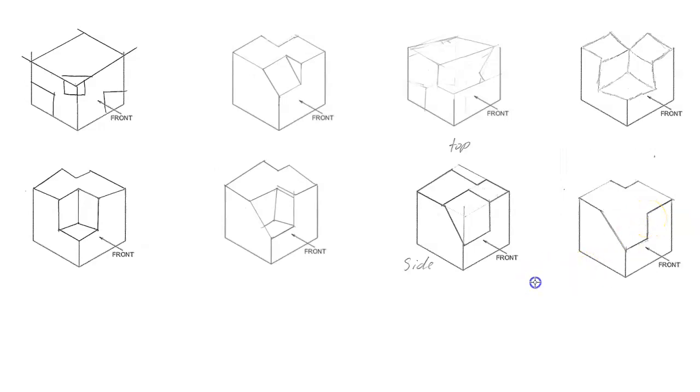So I think that's a pretty good range of what to expect, and hopefully you've learnt some of the things about how we approach where the marking scale is. And if you take nothing else out of this, remember that lines need to be within reason. I'm happy to allow 15 degrees out, but I can't allow 30 degrees out. And feathering. Feathering is no good. Okay, so that's the paper.